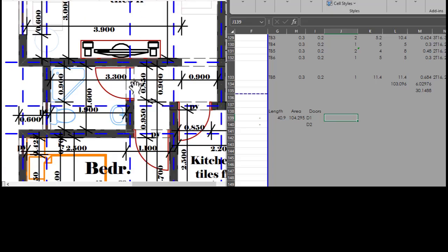So you just cross check door D1, what is the size, door D2, what is the size, okay. So that at the end of the day, you just get the length, the width and the height of those doors, okay. And then you are done. You get by getting the areas. But now that for the one we are using, it's not indicated, so what we'll do, just follow grid by grid, take the sizes. So in this case, we have at grid 3, we are starting with this door,